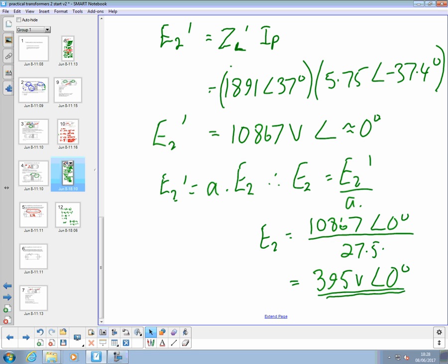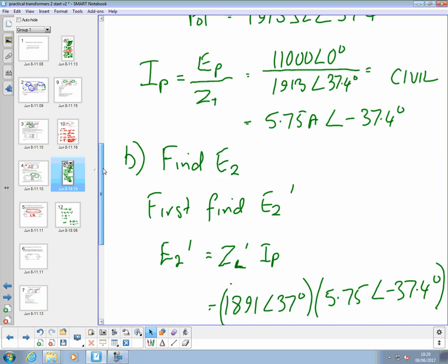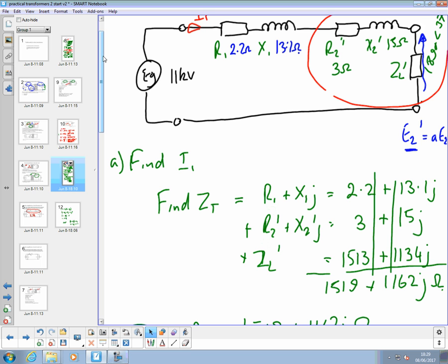Right, yeah. Now, just give me 1 minute, Richard. Okay. So what we've done now is we've calculated that voltage there, 395 volts. So you can see now what's lost across this pair of components and that pair of components, which are the linkage losses between the two turns of the transformer.